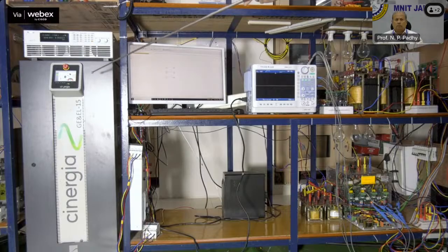while the input side of the emulator is connected to the distribution system of the campus. Also, notice that after the inductors, the wires are passed through the LEM current sensors. For voltage measurements, sensing is done near the MCB input and the sensed signals are connected to the LEM voltage sensor board. The setup is ready for demonstration.